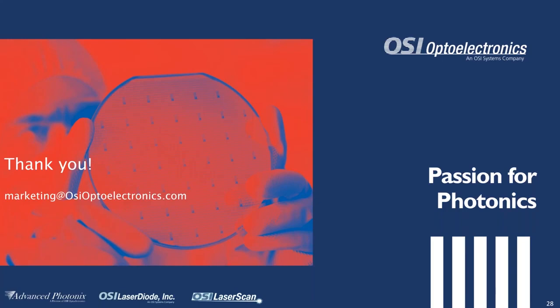Many scientists and engineers are working on improving IR sensitivity of silicon, for example, silicon APD, to allow, for example, high gain at wavelengths above 1000 nanometers. And unfortunately, up to now, the best way to do it is still to increase the thickness of silicon, which will require, of course, applying high reverse bias. So that's the only feasible and most practical way for now.